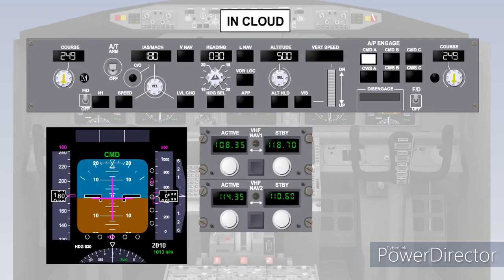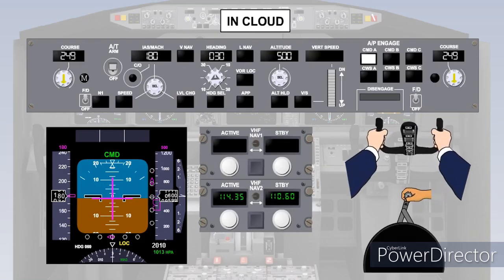A precision approach and landing requires lateral and vertical guidance and minimum values of decision height and runway visual range. Decision height is a specified altitude or height at which a missed approach must be initiated if the required visual reference to continue the approach has not been established. Minimums. Runway visual range is the horizontal range along the runway that a pilot of an aircraft on the centerline can see the runway surface markings or lights delineating the centerline.